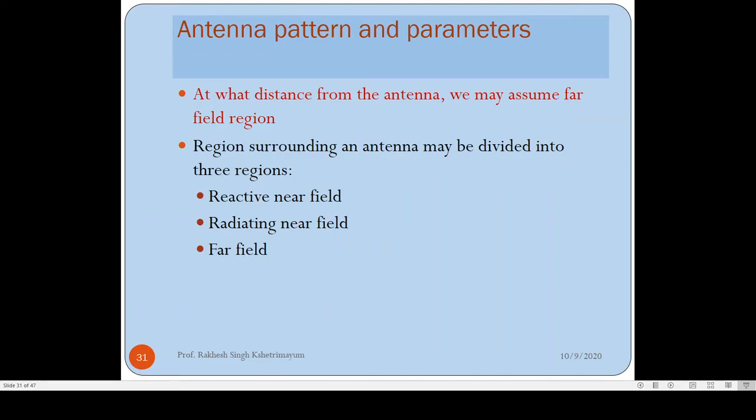And nowadays we have many applications for the far field of the antenna, like mobile communication. Wireless communication usually happens in the far field of the antenna. We also have applications for near field, for example, wireless battery charging, wireless power transfer in the near field. We can also do wireless power transfer in the far field. All these things can happen either in near field or far field. We need to know clearly what is near field and far field distance.